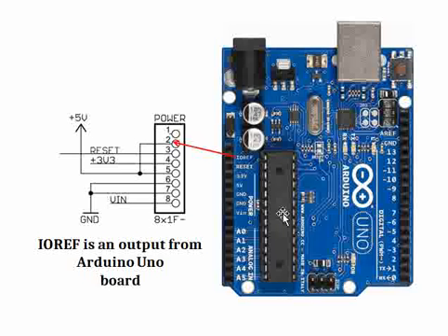And then this is another important point. There is one pin called IOREF, right? This IO reference pin is the second pin in the shield connectors, the IO connectors. You can see from the schematic snapshot here, this is connected to the 5 volts.